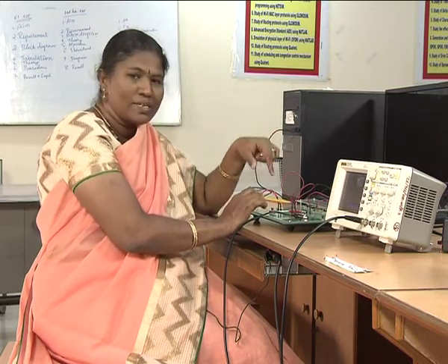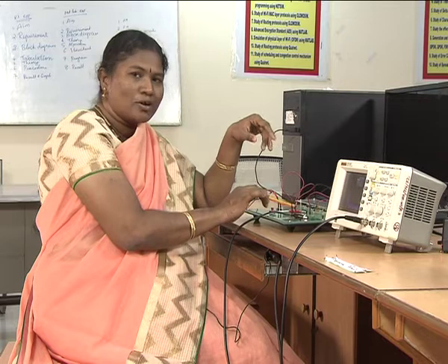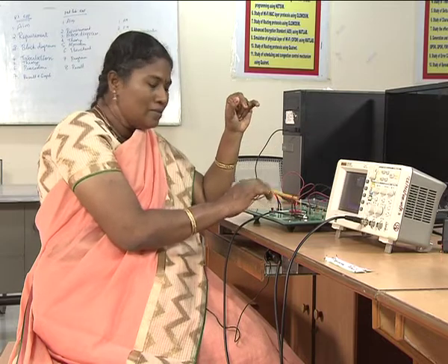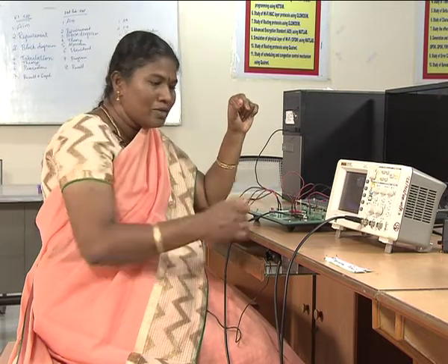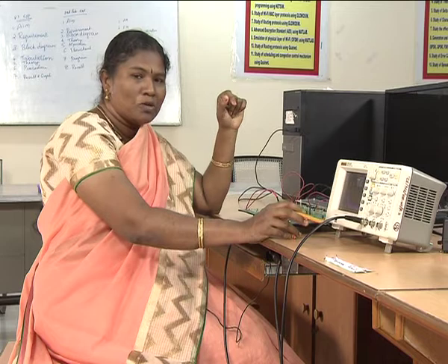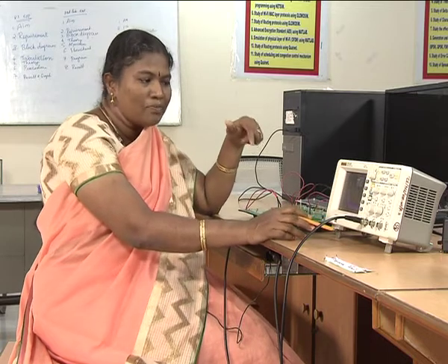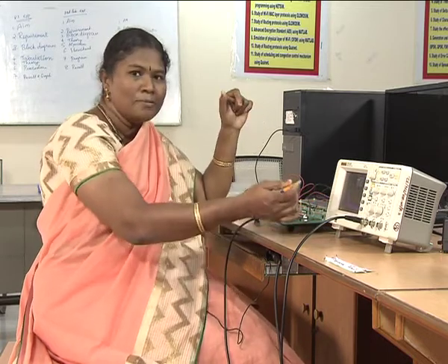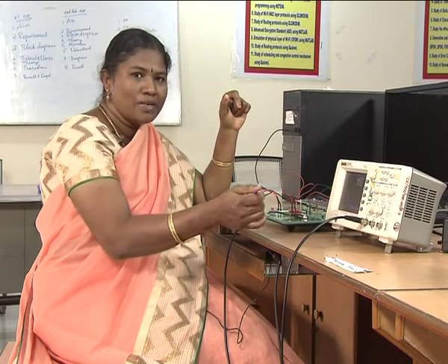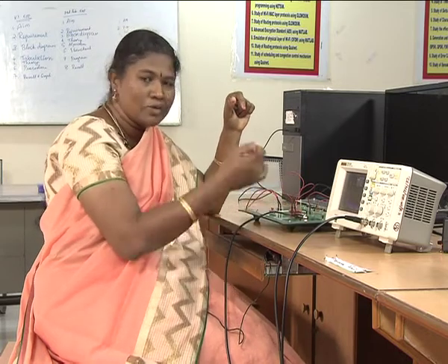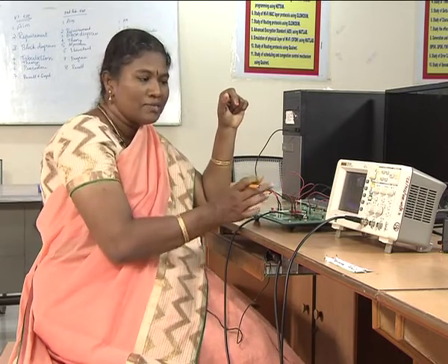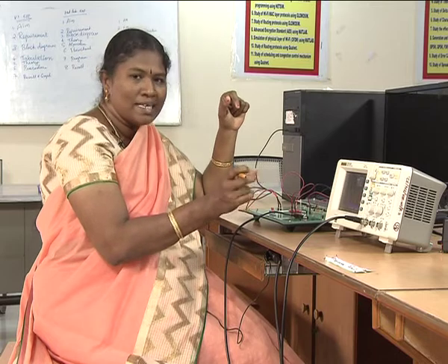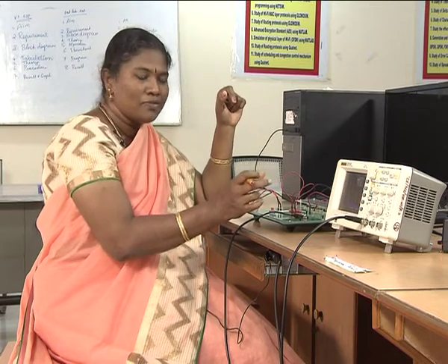With respect to the given input, the FM modulated output is produced at the output of the VCO, which has been viewed using the DSO. So, we can see both the time domain and frequency domain waveforms. In the time domain waveform, we just noted down how the frequency modulated waveform looks with respect to the amplitude of the message signal. The frequency keeps waxing and waning, that is your FM modulated waveform.